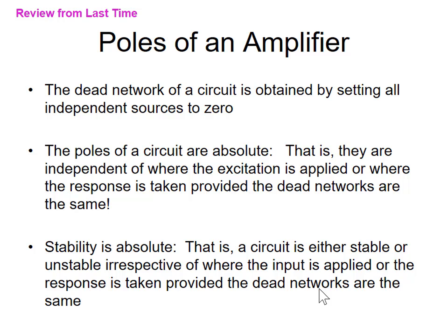So I can say the node voltages are equal to Y inverse, I have to multiply on the left side, Y inverse times the excitation vector. Okay, that gives me all the node voltages. Now, if I want to look at Y inverse, Y inverse is obtained by a ratio of two determinants.